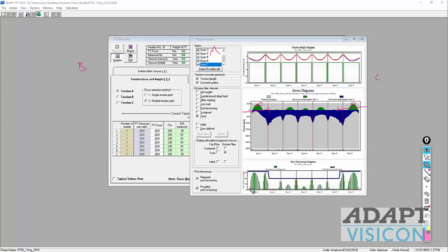The required force is shown by each of these lines at each data point. So we can see we have a much higher required force near spans 1 and 7 versus the interior span. So our actual force, 32 down to 20, does this kind of step curve here. That's the actual force required.